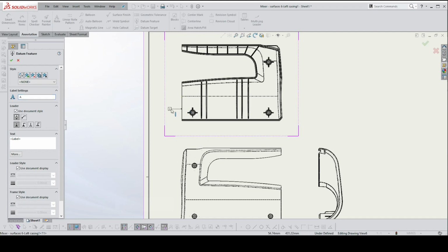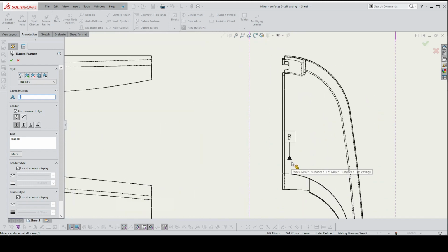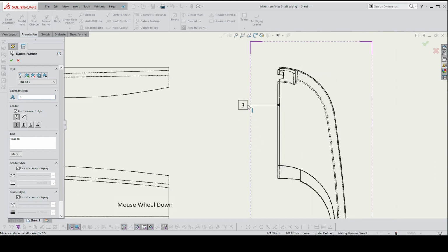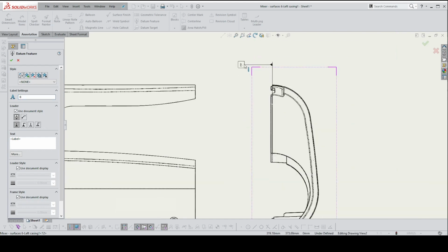If you click on that and drag it out, you should be able to pull it out of the way, and that indicates your first datum, right? So that's actually not really the best first datum. The first datum should be this line here. The reason I'm choosing this one is because that is the parting line for your mold. So that's an obvious place from which to dimension anything, especially if you're talking to toolmakers. So that'll be your second datum.